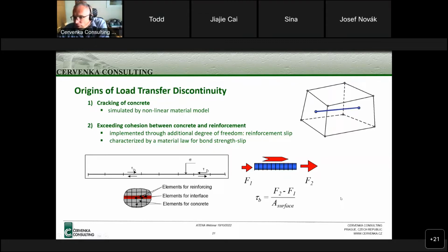Yes, this is a good question. I think the definition of these convection coefficients and emissivity is basically a whole area of research. But in the literature you can find these values. Even if you make a search on the internet, you can find them for typical situations, for example the convection coefficient for a concrete wall, and it very much depends also on whether there is wind and so on.